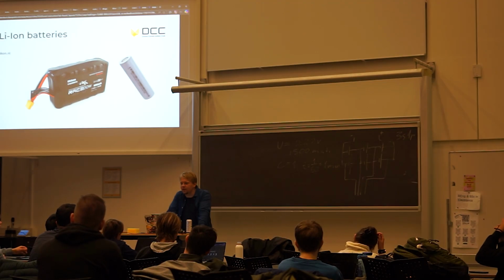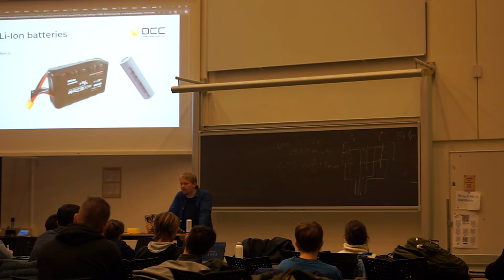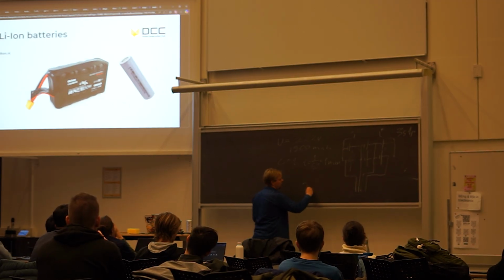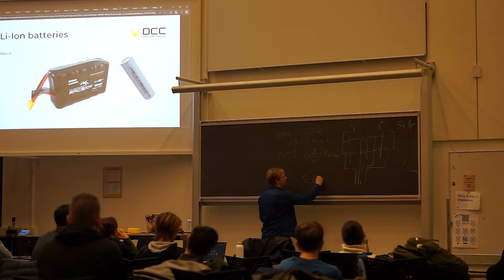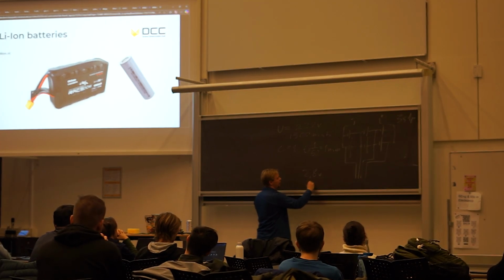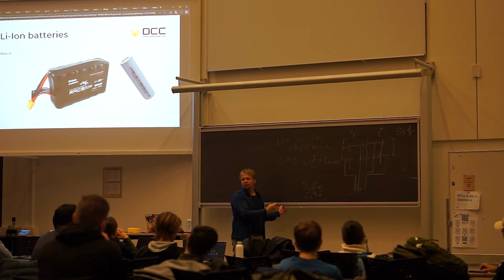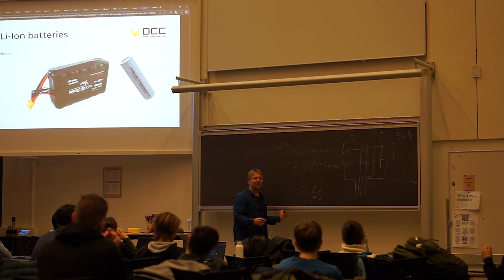Also, because there are different battery chemistries, some lithium-ion batteries can be discharged to most of them about 2.8 volts per cell, and some can go even lower, to 2.4. If you do that with any LiPo, it's going to be totally done. You could still get light out of it. I'll show you that later.